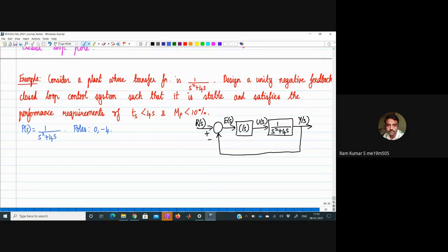No, sir. Marginally. So it depends on how we want to visualize it. We can say marginally or critically stable, but it's certainly not stable, right? We can see that a step input will lead to the output becoming unbounded, and that's something we can immediately observe by the presence of a pole at the origin.